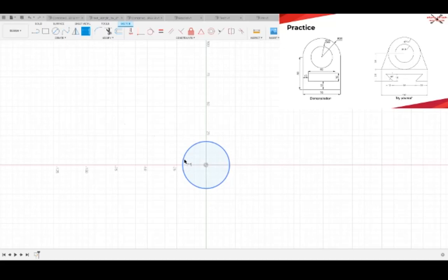So you want to click this little guy up here in the corner, that's a sketch dimension, and actually define its value, which is why I had mentioned the visible text, because this is kind of important. Your dimensions are what actually constrain your shape to adhere to a specific size or shape. Obviously with a circle, it's only a circle, but when you get to things more complex, such as combined arcs with lines and such, they tend to be more open-ended and need more constraint to go with.